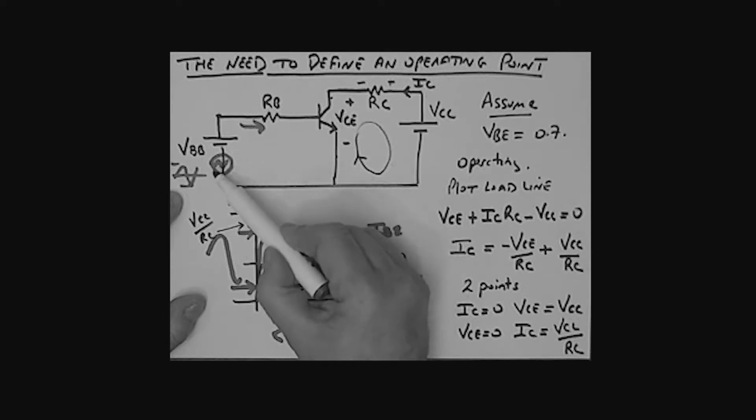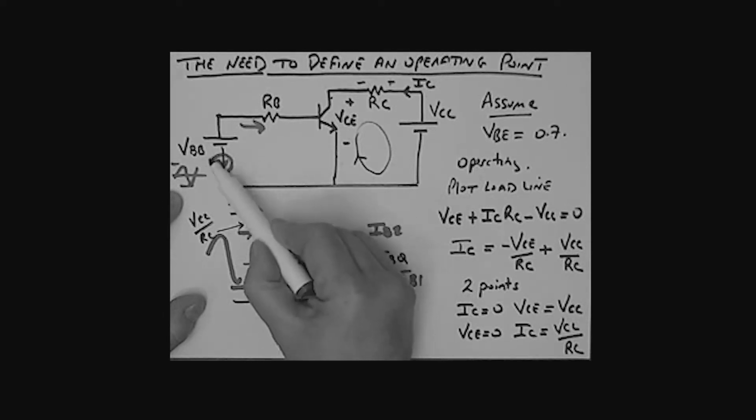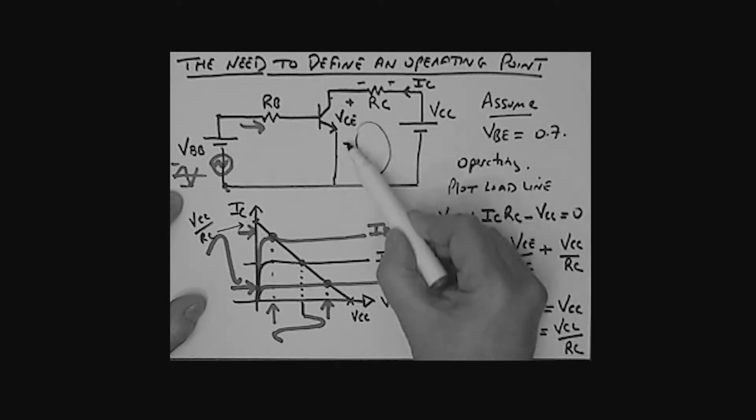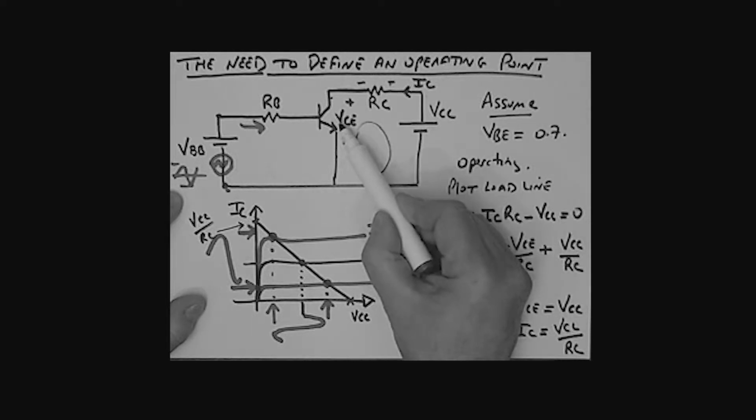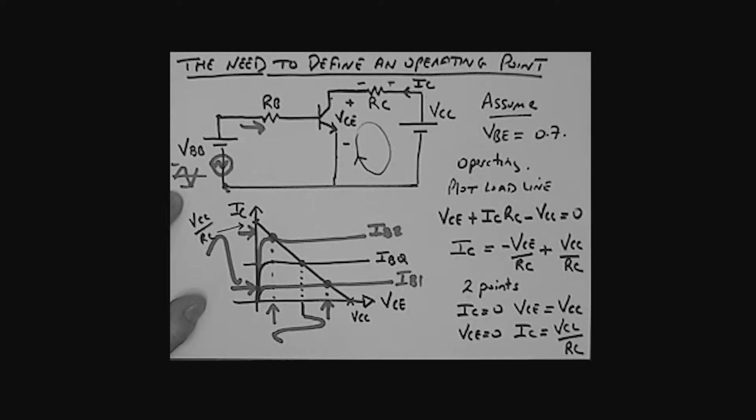And you can argue a small voltage variation here is producing a much larger voltage variation in the collector emitter voltage. Okay? Now what does this say to you? One other thing it could say to you is, look, the establishment of the operating point. Where do you want the operating point? Here the operating point was sort of in the middle, wasn't it? Between this point here and really the zero. Not quite in the middle, but sort of in the middle.